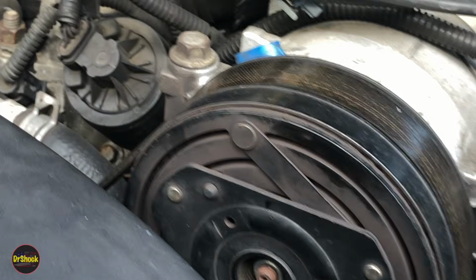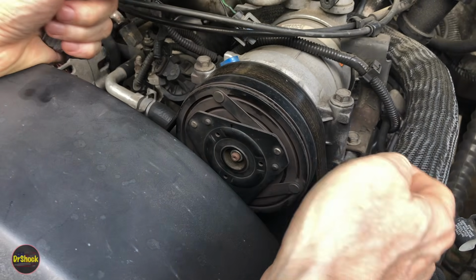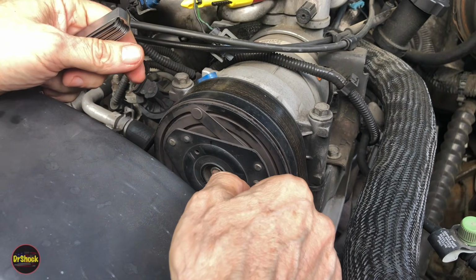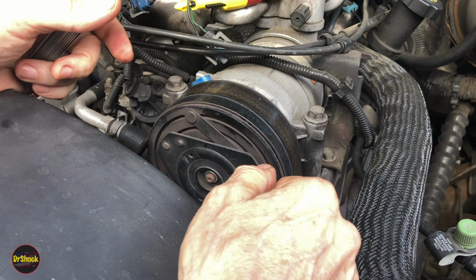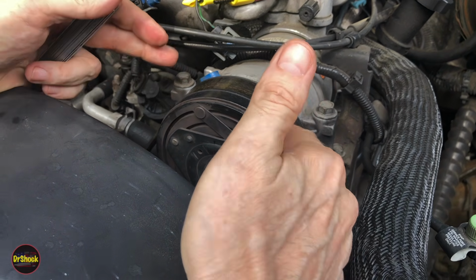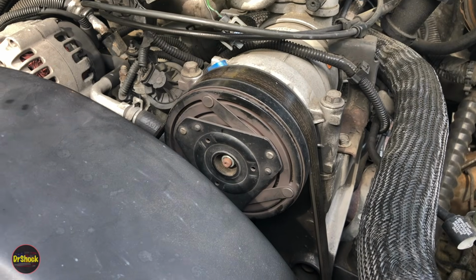So what we've got is the air gap is anywhere from 2 to 4 thousandths off. Is that enough to prevent the magnet from closing it? No, I don't think so. If it was 10 or more, I'd be inclined to adjust this gap as a possible fix, without having to replace anything. But for just 4 thousandths, I doubt that's a problem.